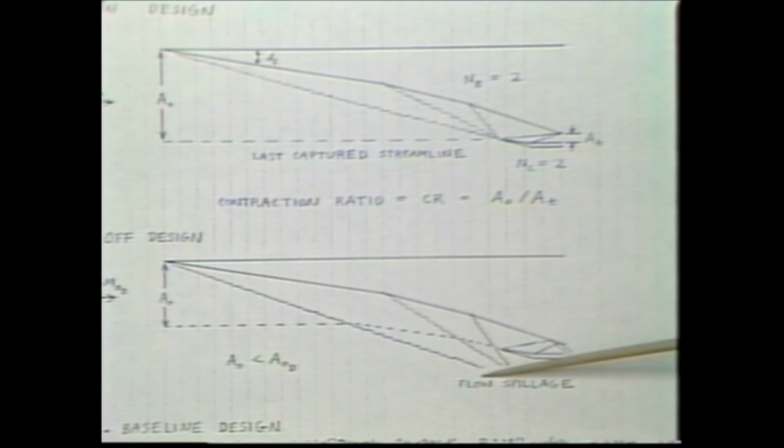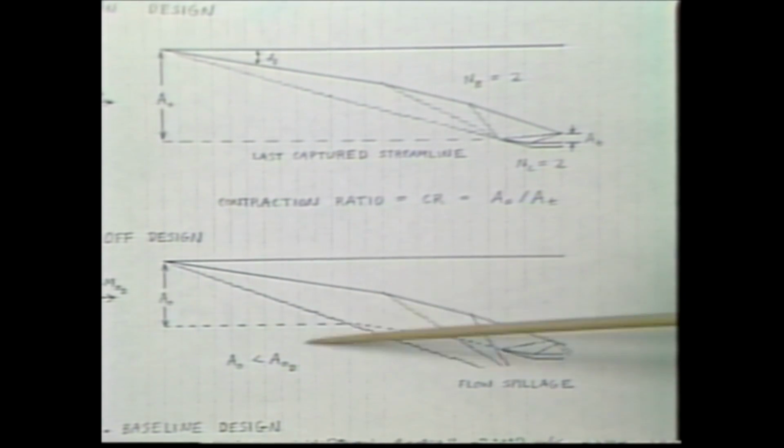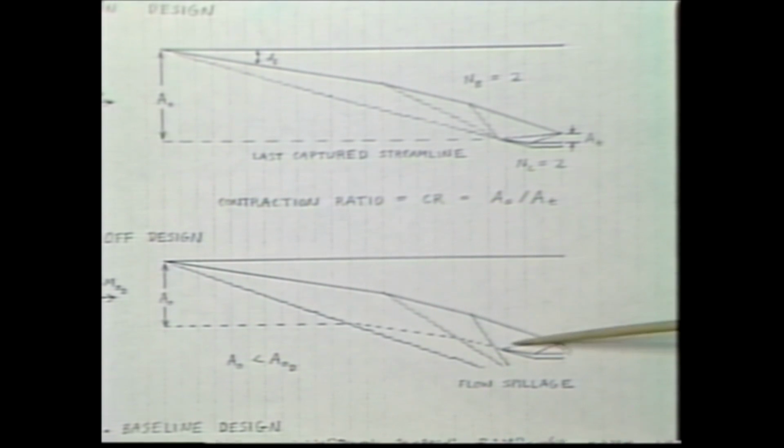All these ramp shocks are not going inside the inlet, which means that they are spilling flow, pushing flow around the cowl. In other words, you've pushed flow through these shocks and compressed it, but it's not going through the engine to produce thrust. That's called spillage drag.